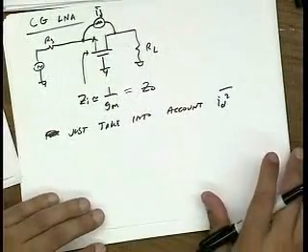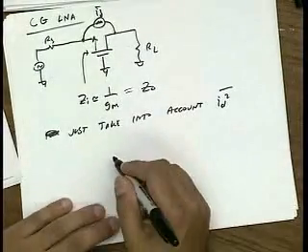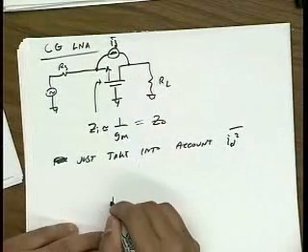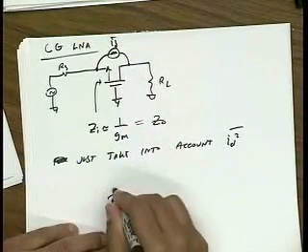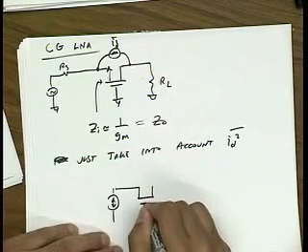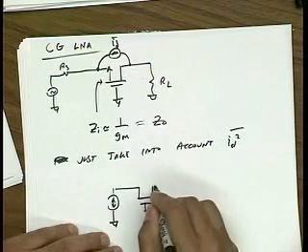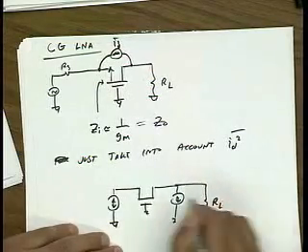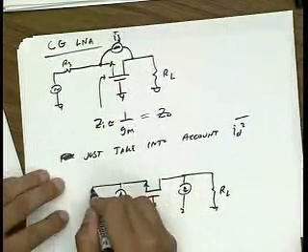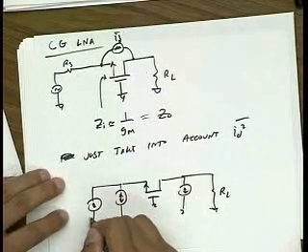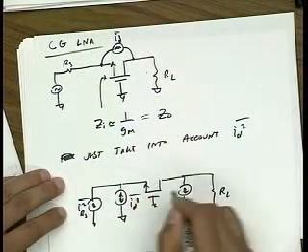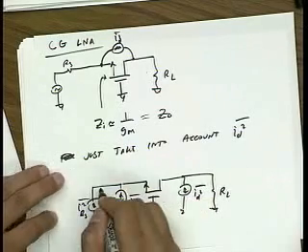In other words, I can break up my circuit. What I can do is take this current source and break it up into two current sources in series, let's say connected to ground. Okay, this makes the analysis a lot easier. This is iRS. This is iDrain. This is iDrain.